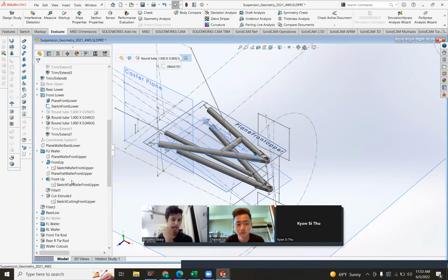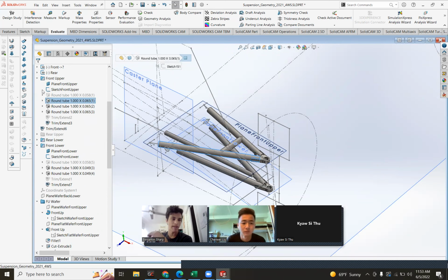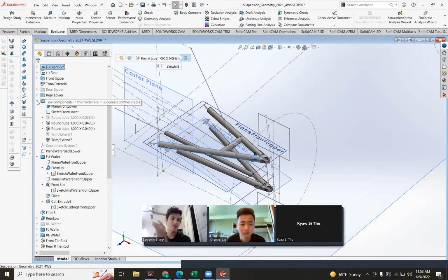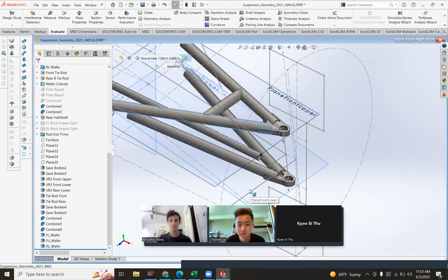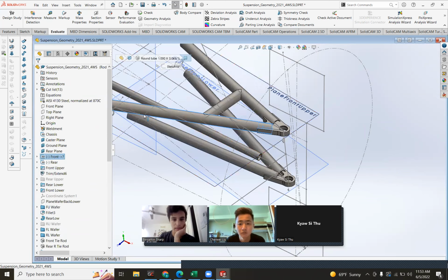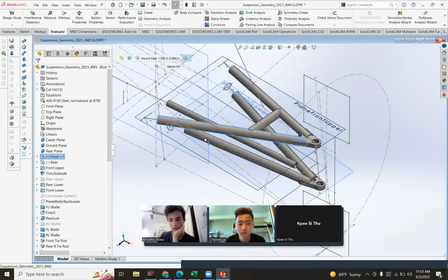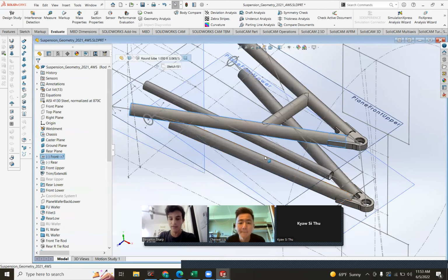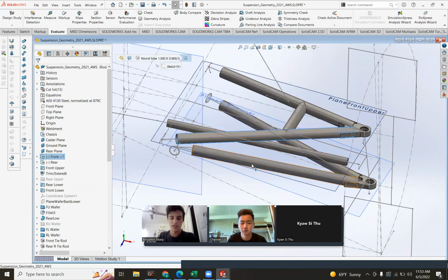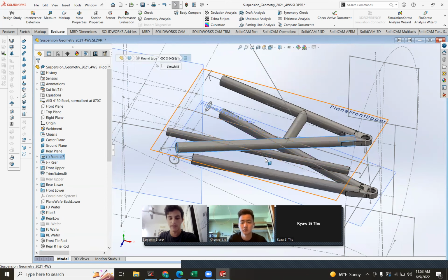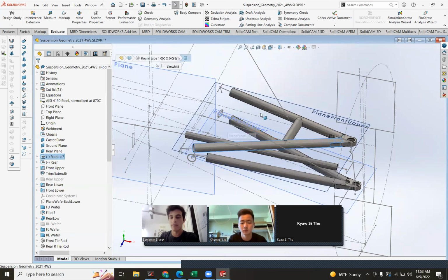Yeah, so that's, I don't want to make it sound like it's simple, like, oh, that's all there is to the A arms, because they're really tricky. But refer to this CAD because I did a couple things wrong. Most notably, I pointed out in the sketch how you should make room for the rod ends at the end of your arm. I didn't do that at first, and I had to cover it up with a bunch of features, and that was a pain. It's way easier if you have a line that's the correct length first. So you should do that better.